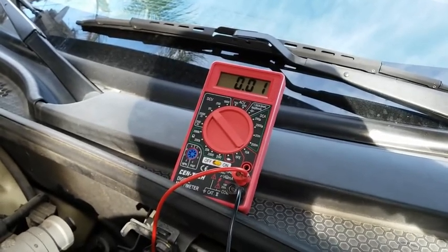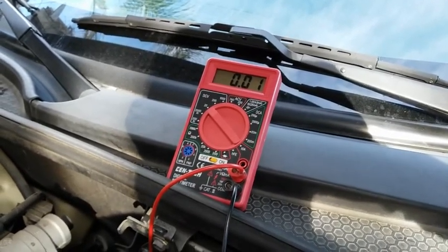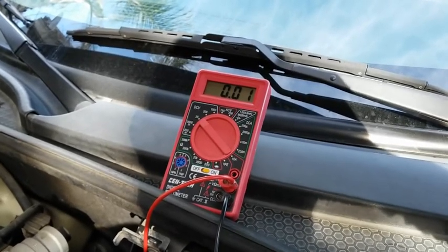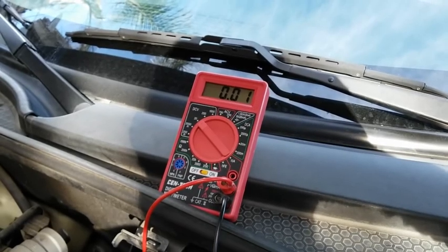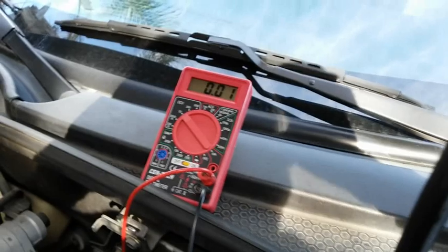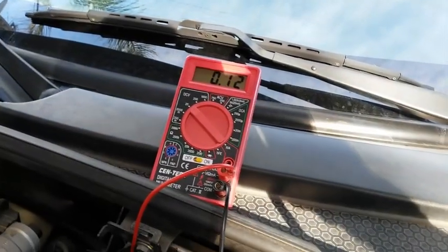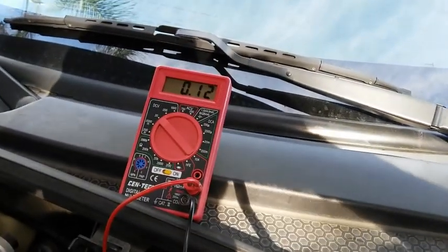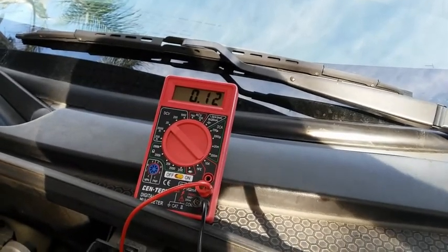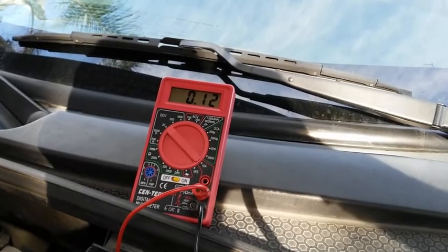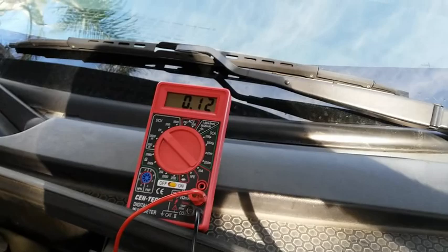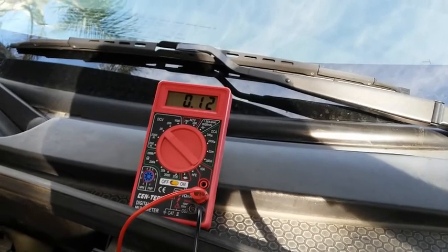The next step, I'm going to turn the key on, engine off, and this voltage should read approximately 0 volts. Remember, this is a normally closed switch, so on the pull down design, our voltage should read approximately 0 volts. Alright, with the key on, engine off, our voltage is approximately 0.12 volts, which is a good sign. Remember, on the normally closed switch, this voltage should be approximately 0 volts, and as you can see, it's 0.12.